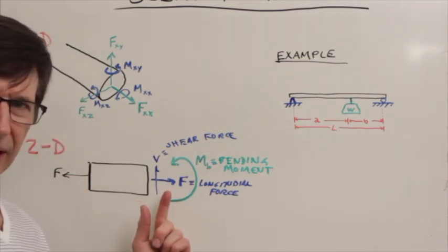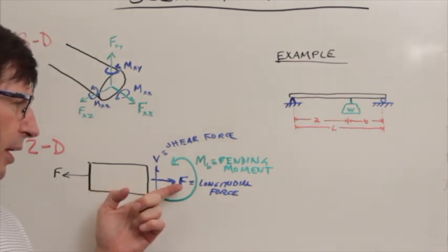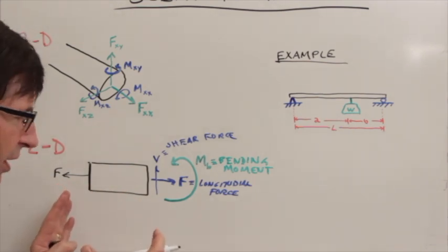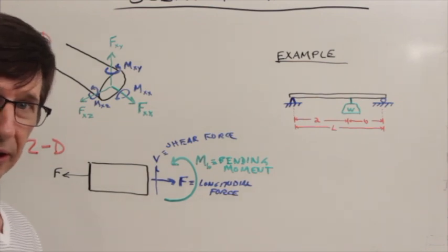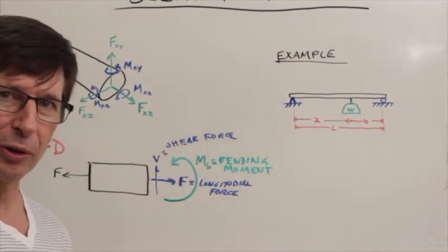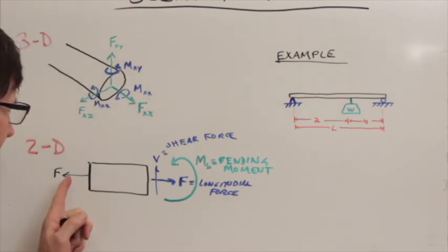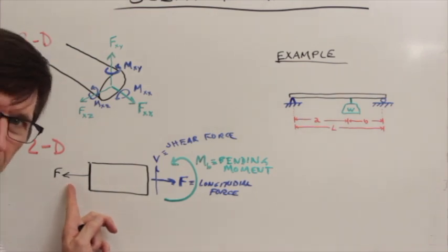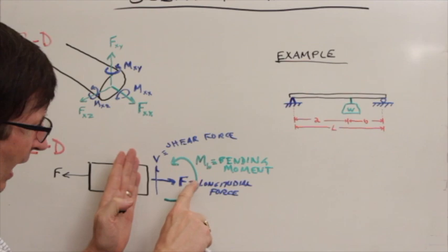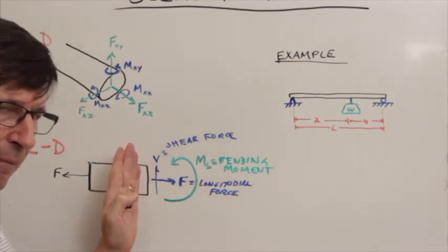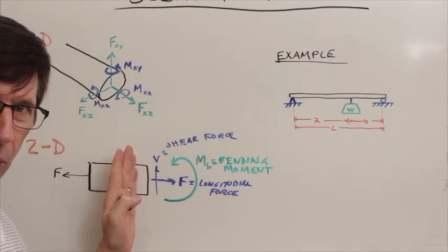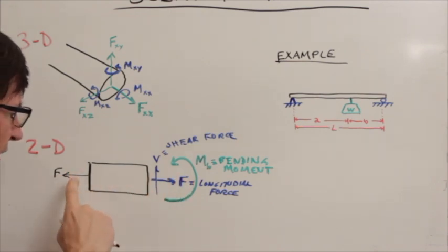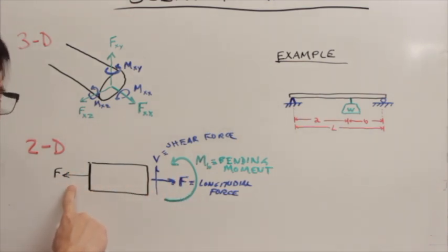And we don't want to say we have a positive force on one side, negative on another. In this beam, the force is going to be positive, something that in other jargon we call tension. That means that this force has to also represent a positive orientation. The way we think about it is a force outward on our end is a positive tensile force. And on this side, this force is outward, balancing that one. So this too is a positive or tensile force.